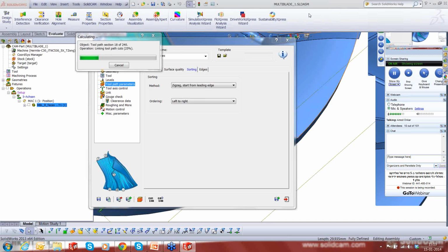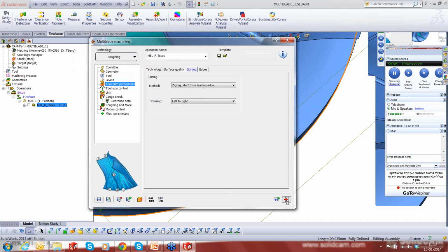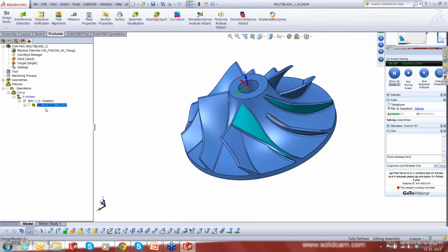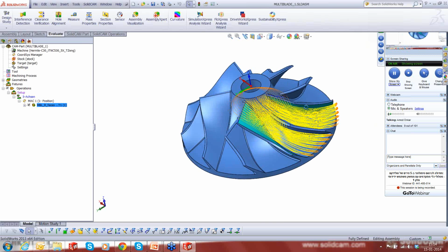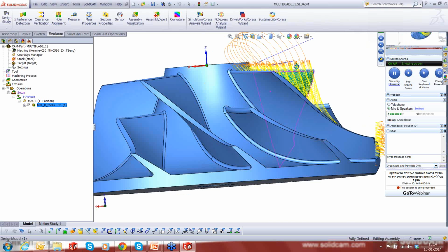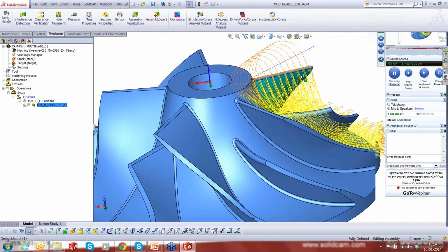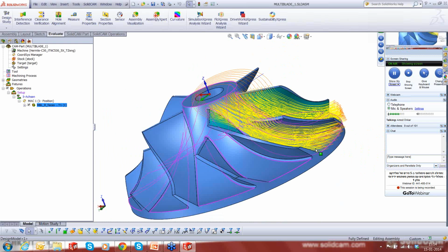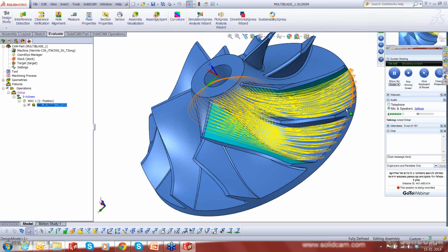Okay, it's almost done. We come out of the toolpath calculation and show you the toolpath straight away. It's much nicer now. You can see how the connections are happening, very nicely connected using the blend option. It's not jumping every time to the clearance plane to do any kind of linking, but most of the links are happening within the layer. So extremely nice and clear.